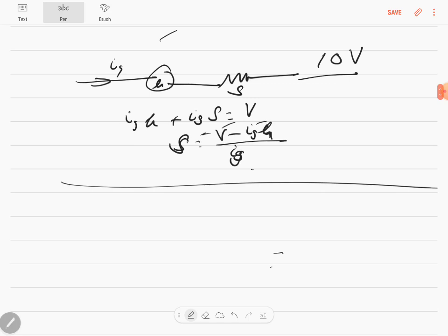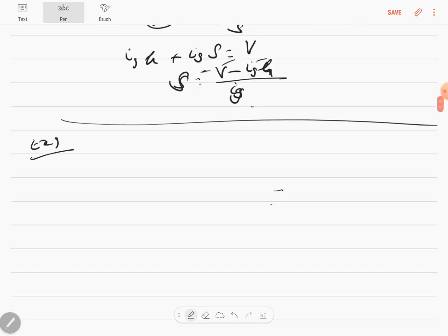So the next sum is example 91, where in a galvanometer there are 10 divisions per milliampere. That is the configuration of the galvanometer, the divisions for every milliampere. But they are saying the internal resistance of the galvanometer is 60 ohms. If a shunt of 2.5 ohms is connected to the galvanometer, then there are 50 divisions in all. Okay, 10 divisions is for 10 to the power minus 3 amps.